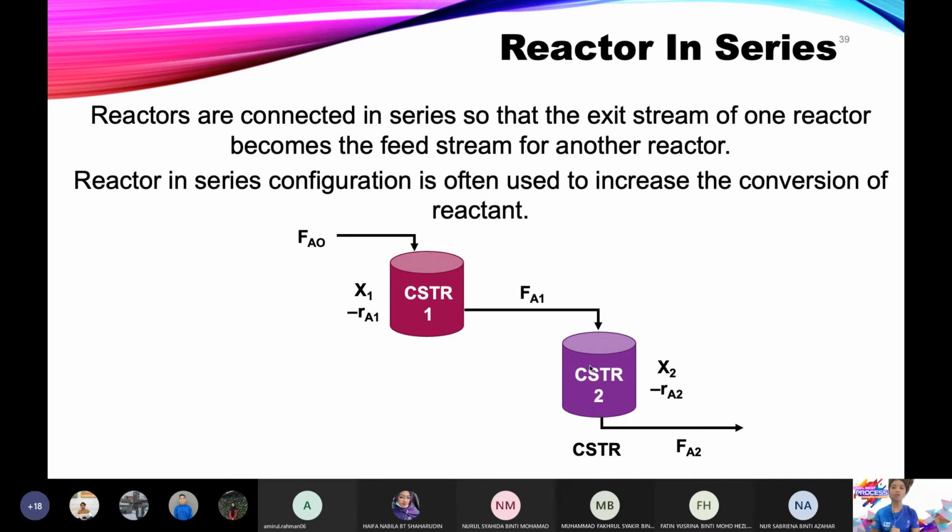In other words, conversion does not reset. What do I mean by this? Because students already get confused about conversion. In the first reactor we calculate based on the original 100 that enters. In the first reactor it converts, as I told you, from 0 conversion to 40% conversion.